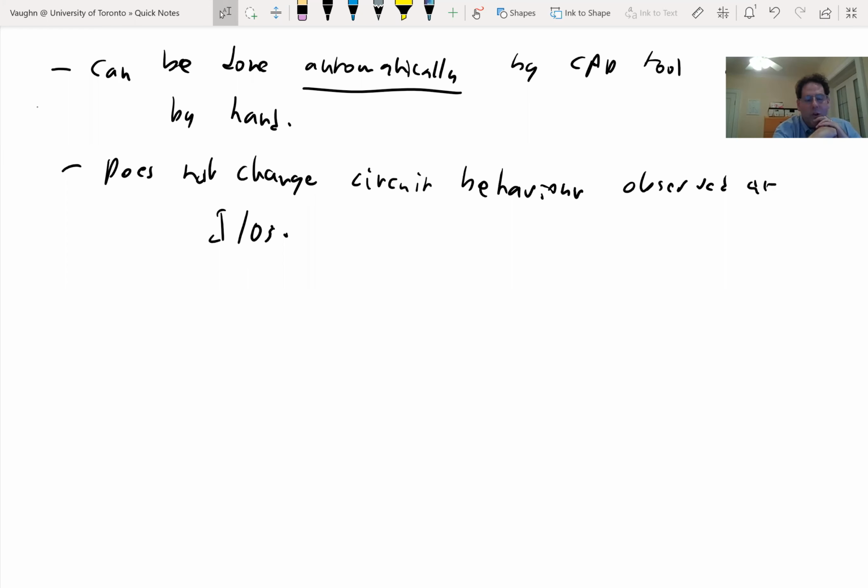That could be true, although if retiming always made it better, then probably the CAD tool vendors would be happy with that. They'd just say, you don't have to worry about it anymore. So I guess that one's a plus minus. If basically you could write arbitrarily unbalanced RTL and the retimer just made it all the same speed, the CAD tool vendors would probably consider that a win. Maybe its performance wasn't very good, its applicability was limited. True, initially it wasn't that good.